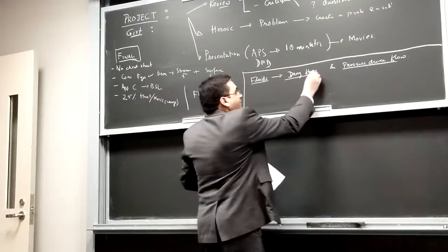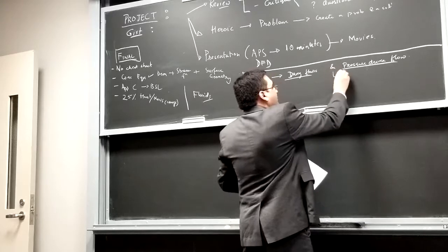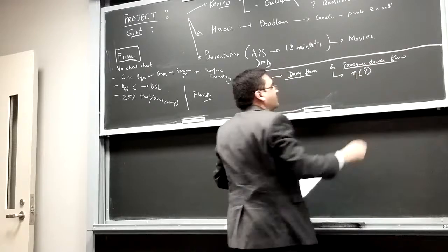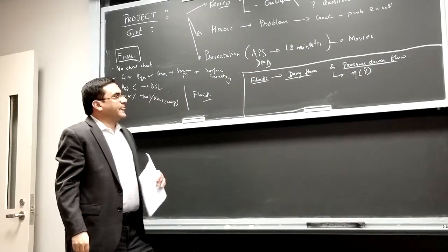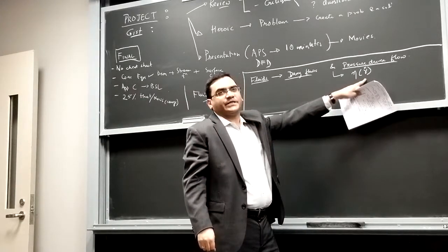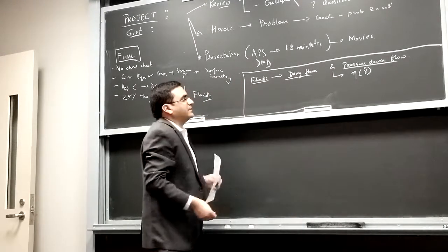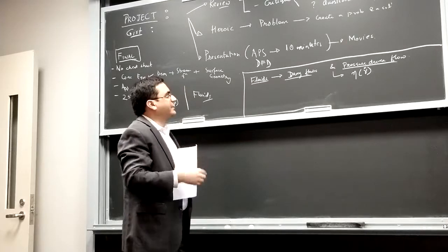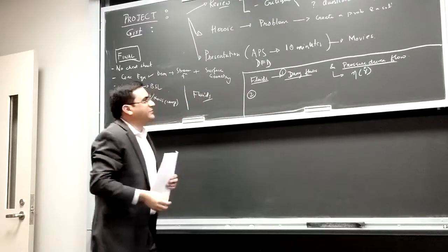Drag flows and pressure-driven flows are also used for measuring viscosity, and once you measure viscosity, especially for non-Newtonian fluids, because viscosity itself is a function of deformation rate, that allows you to have better control and understanding of processing conditions. So those two come in handy there too. You've done problems where you've looked at cone and plate, fluid geometry, and so on. So that's one set. These were all more or less one-dimensional flows.